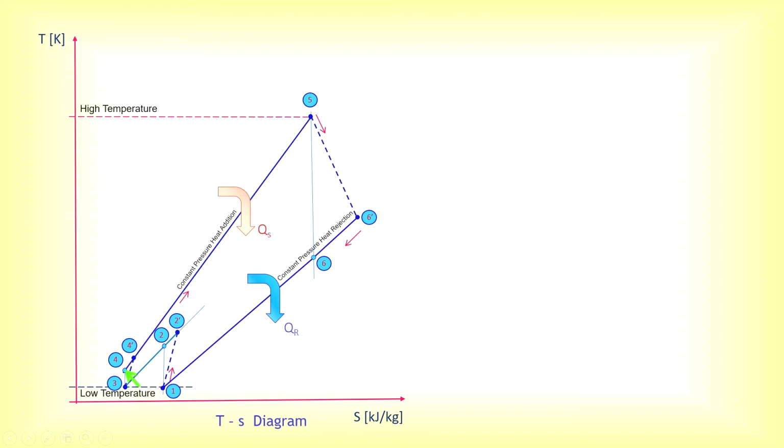Okay, so this is for a closed gas turbine unit. For a closed gas turbine unit, you can follow state 3 to 4. But with irreversibilities, we have state 4 prime. So from 4 prime, it will undergo constant pressure heat addition or heating in the combustor or in the combustion chamber until it reaches its maximum temperature. Then it will go into the turbine where it undergoes isentropic expansion.